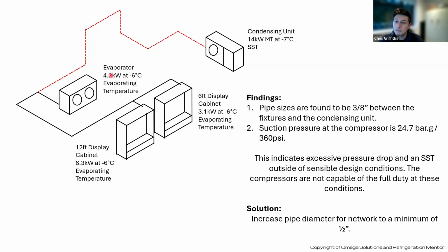So what our solution for this would be, if we had that as 3/8 inch, we'd increase the pipe size. I imagine 90% of people out there, technicians, would come to that same conclusion as well. If it's too small, you make it bigger. Up you go.